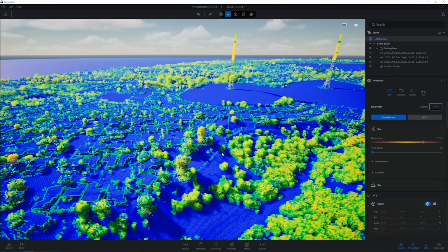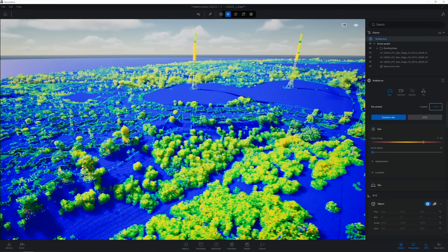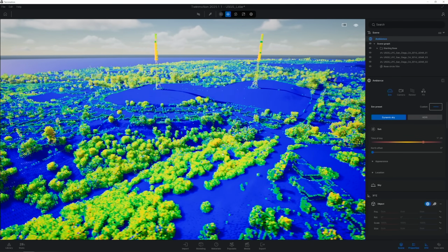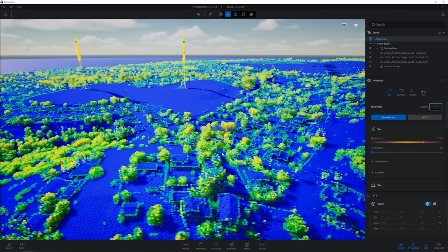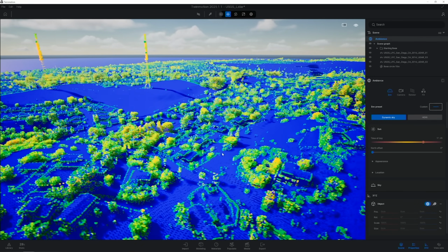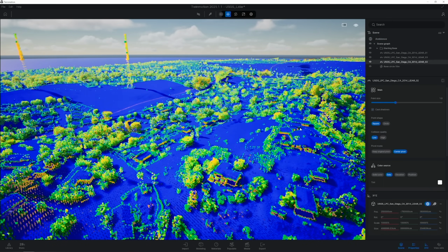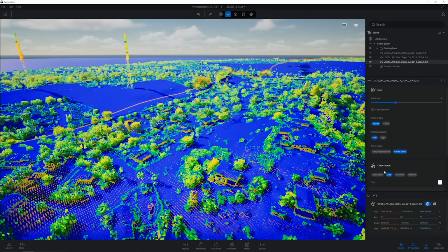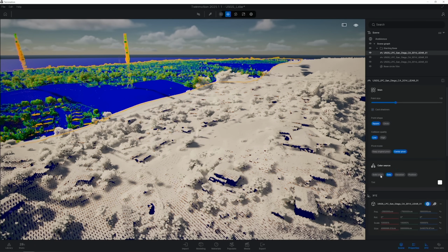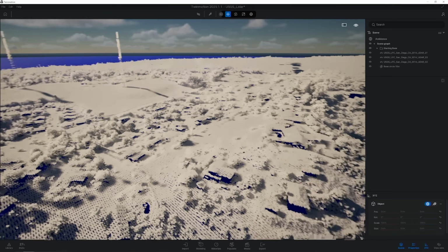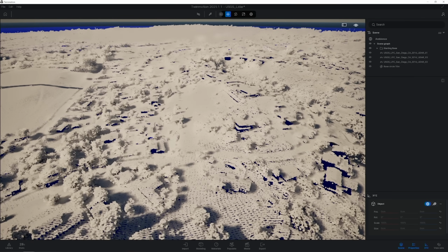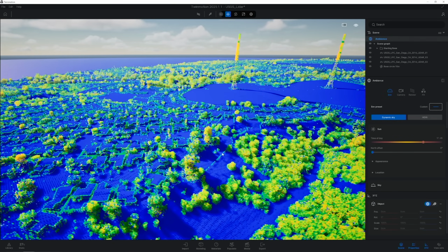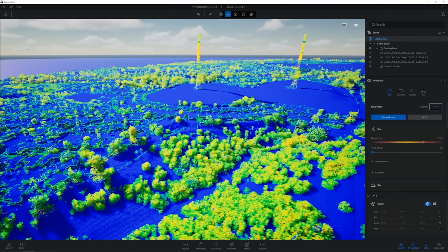And this is that data set just directly inside of Twinmotion. I split it up into a couple pieces, 3 pieces, but it's still 1.5 by 3 kilometers wide, 63 million points. And it's a pretty cool way to just fly around this 3D LiDAR data in real time. We give you the option to replace the color with a solid color of your choosing. You won't be able to do any other complex management of the point clouds like you would in software dedicated to that. But if you have your color data baked into that first main channel of the point cloud, then it looks really cool in Twinmotion.